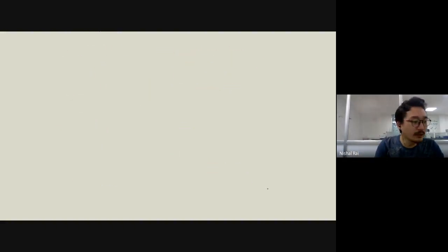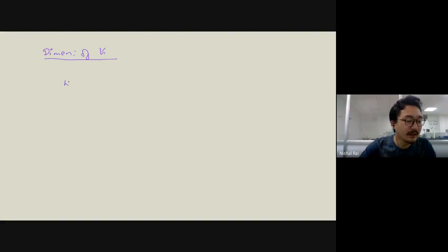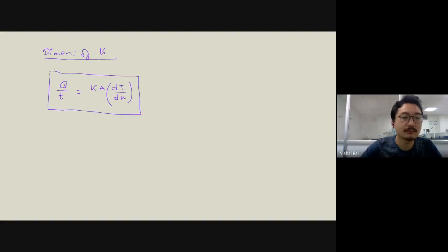Now next we are going to do what? The dimension of K. So what will be the dimension of K, of thermal conductivity? Now again, what you can write is Q by t can be written in this form: K A into del T by del X, the temperature gradient. Clear? Is this point clear?